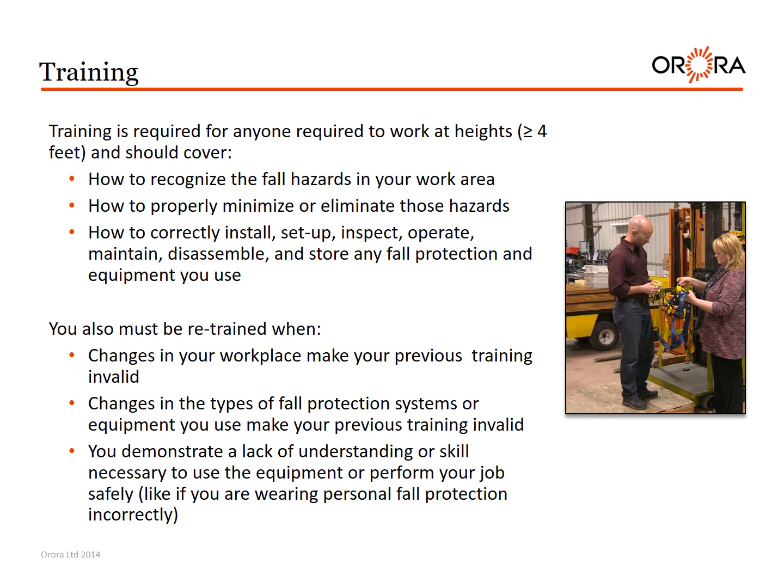Training is required for anyone required to work at heights of 4 feet or above, and should cover how to recognize the fall hazards in your work area, how to properly minimize or eliminate those hazards, and how to correctly install, set up, inspect, operate, maintain, disassemble, and store any fall protection and equipment you use.